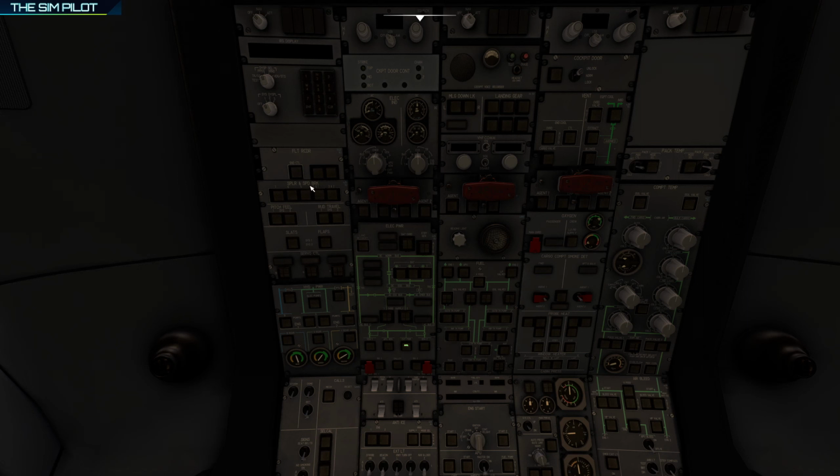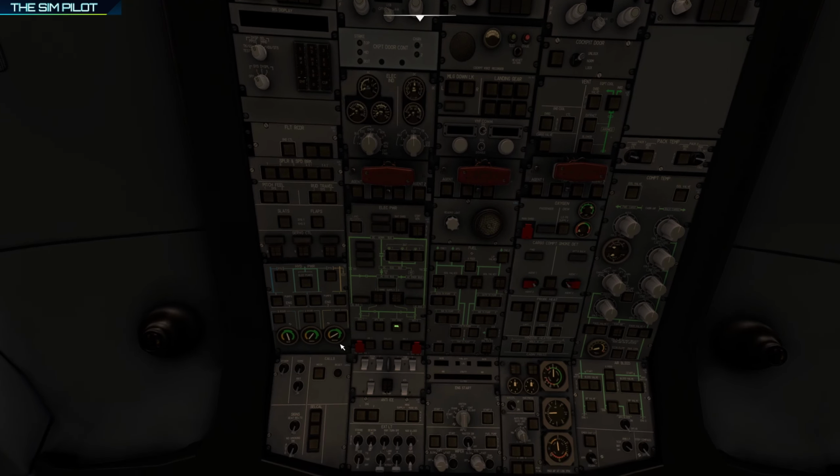Below that is the flight recorder. Below the flight recorder, these are various flight control systems that control the spoilers and speed brakes, pitch and rudder, slats and flaps, and servos. Below this panel is the hydraulics panel: blue, green, and yellow systems, and they have dedicated gauges to display the hydraulic pressure status of the hydraulic system.